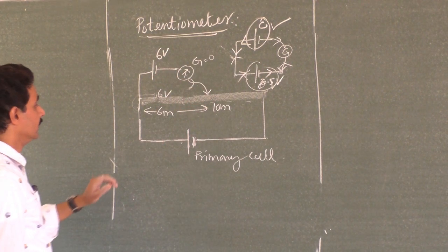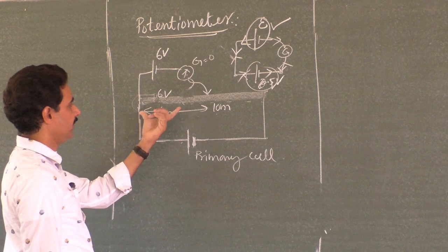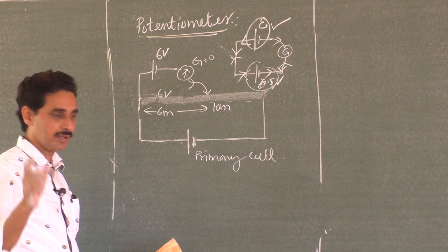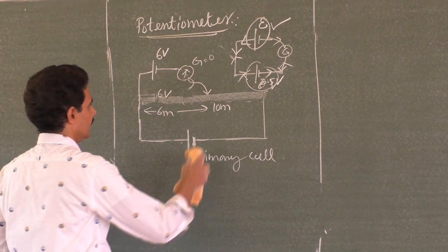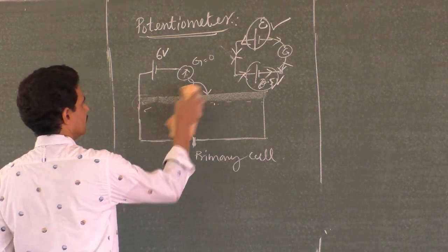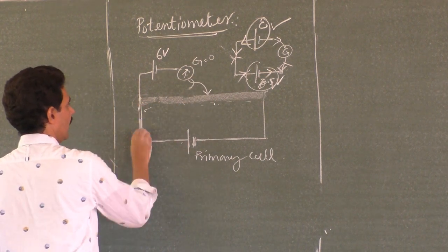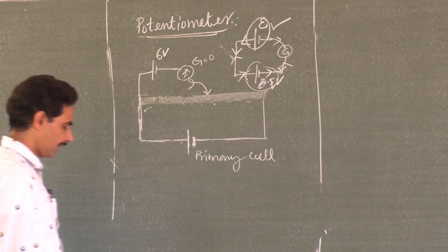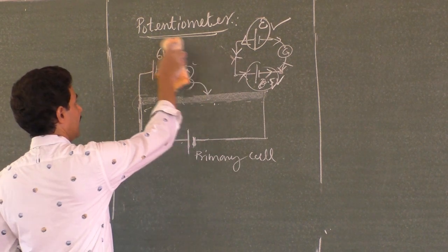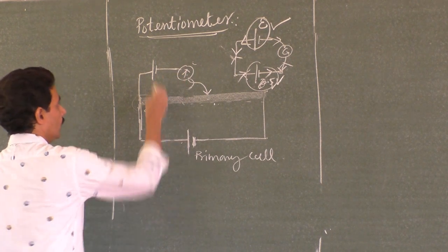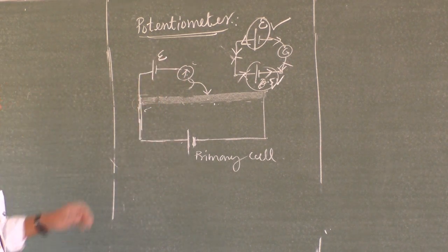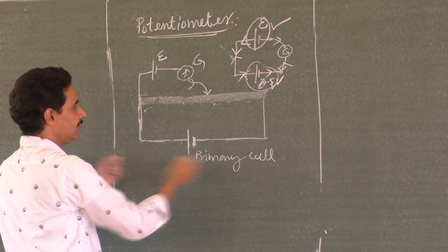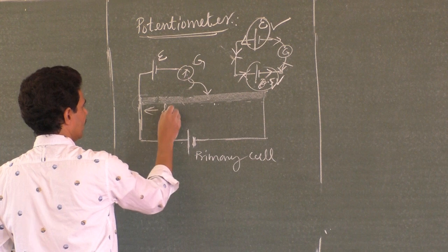It energizes the whole circuit. Okay. Sir, if I don't know what is the EMF of this, can I find out what is the EMF of this cell? Yes, comparison method. That is what you did in the laboratory this year. Now, I rub this. So what I'll do is, I don't know how much voltage drop is occurring in each part of the wire, but still, if I am given a battery of unknown EMF, say E, what I can do is, you connect that battery along with the galvanometer, keep on moving this till you get the balancing line 0. Say this is L1.